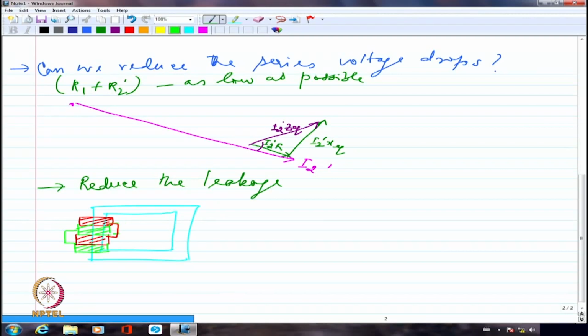We can do that also, that's another way. Concentric coils, we call them concentric coils. This is in case both of them are of comparable voltage. The comparable voltage thing will come up when I want only isolation to be established. Maybe I have a 220 volt system, another 220 volt system.